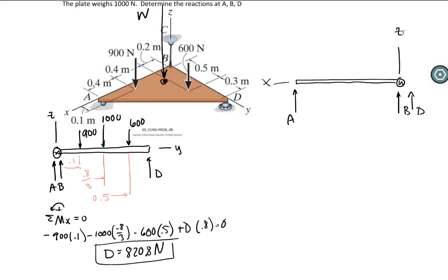Then from this view, we should be able to see the 600 and the 1000 and the 900 looking backward like this. All right, let's look at the lever arms carefully. 600 has a lever arm of 0.2, pretty obvious from the drawing. How about the 1000? 1000 again would be whatever this dimension is, it'll be 1/3 of that. So this looks like a full meter, and so the 1/3 dimension should be 1/3. Then 900 has the lever arm of 0.6.